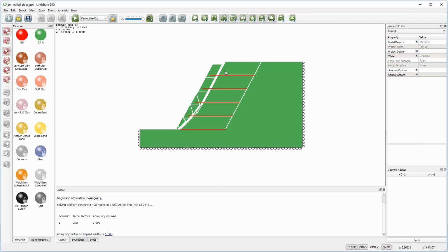The reinforcement stays fixed and the soil just shears past it, and there's a bit of pull out of the front end of the reinforcement from that sliding wedge. So conventional analysis might consider two wedges further back, but this is in fact the failure mode that is most likely in this particular case.